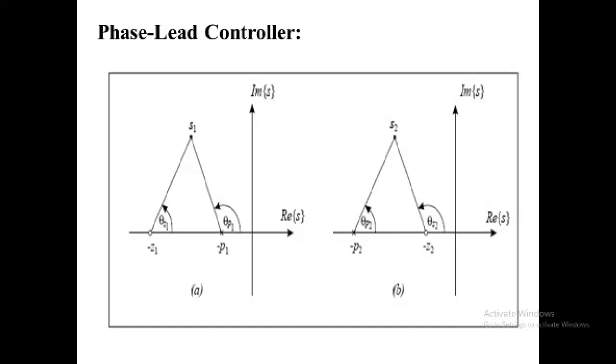So how can this improvement of the steady state error be done? As in the previous chapter, the steady state error can be improved by increasing the type of the feedback control system, in other words, by adding a pole at the origin to the open loop transfer function. This is the simplest way to achieve this goal, and it is added in series with the system. A PI controller is defined so that Gc(s)G(s) = Kp (s + Ki/Kp)/s times G(s). Since this controller also introduces a zero at Z = Ki/Kp, the zero should be placed as close as possible to the pole. In that case, the pole at P = 0 and the zero at Z approximately equal to P act as a dipole.